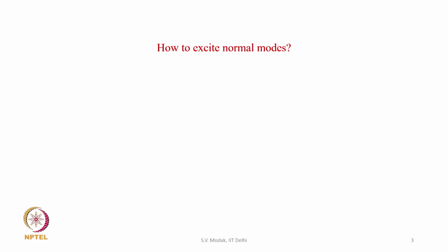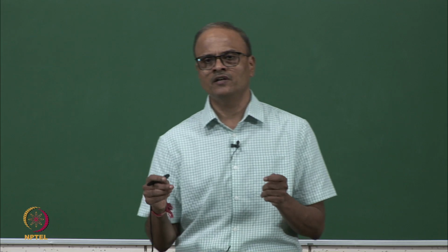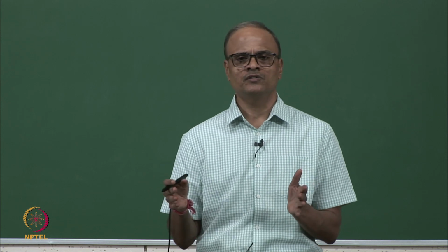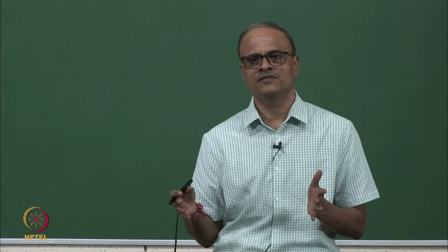Now how to excite normal modes? What we do is that we apply harmonic forces of the same frequency on the structure at multiple locations using vibration shakers. The idea is that we excite the structure with forces at multiple locations and the frequency of all these forces has to be equal, so that the structure vibrates with a single frequency.